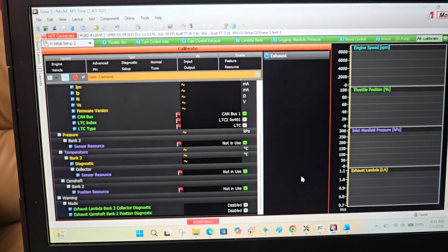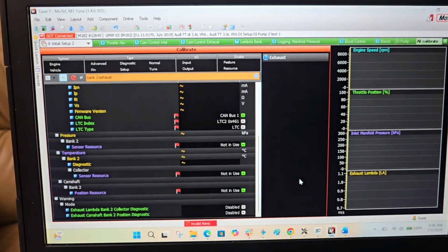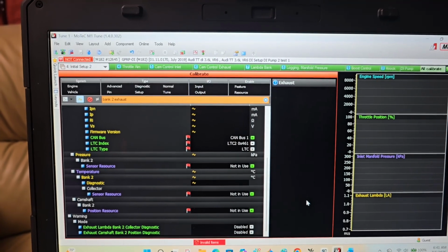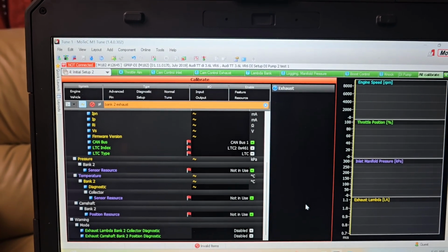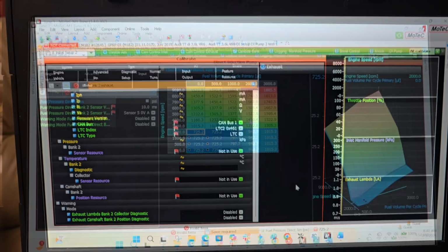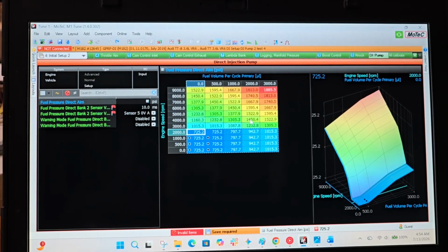So of course you probably already saw the video with just a couple screenshots and how I set up the dial indicator for the cam lobe itself, and also the degree wheel on the crankshaft. But while setting up my fuel pressure direct injection table, I came across some great information. A target of roughly 725 to 870 psi, roughly 50 to 60 bar, is the industry gold standard for starting and idling a medium displacement direct injected engine.